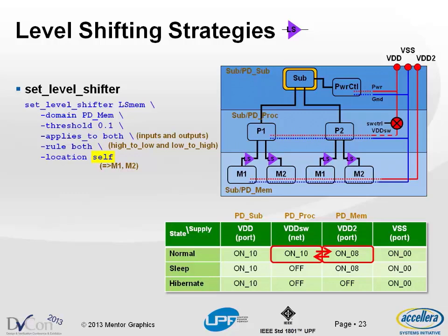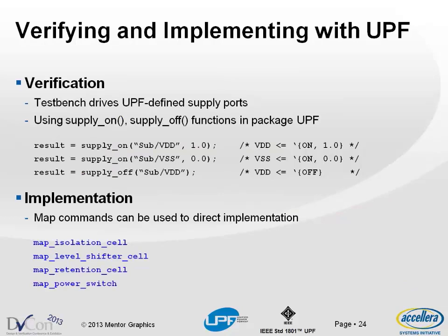One thing that is different here is that in UPF 1.0, there was no provision at all for providing power to level shifters. There's sort of an implicit assumption that level shifters would be powered by the same supply that's driving in and the same supply that's driving out. That's changed in 2.0. And since they're just level shifters, there's no control, so there's no issue about control signals existing. So that was a quick overview of 1.0 UPF.